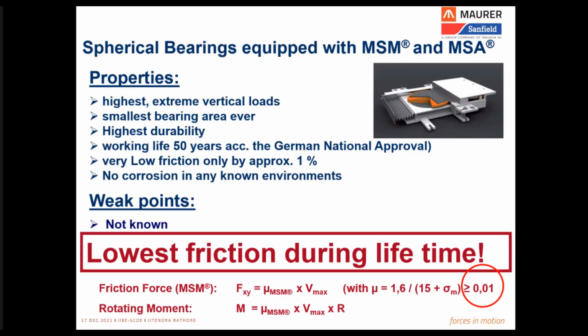Let me also tell you at this point of time that aluminum alloys are not the only choice being used in bearings. In certain parts of the world, certain countries, they are also going for complete stainless steel bearings. If you remember, I told you a few slides before that there is a thin sheet of stainless steel attached to the main steel component to slide against the sliding material. Thin sheet because stainless steel is comparatively, to structural steel, very costly, 5 to 6 times costlier.